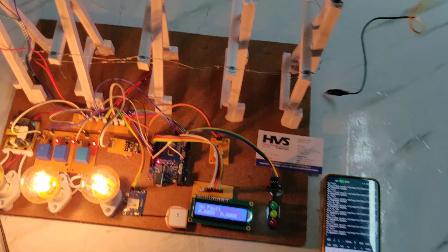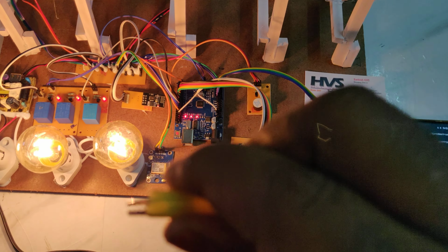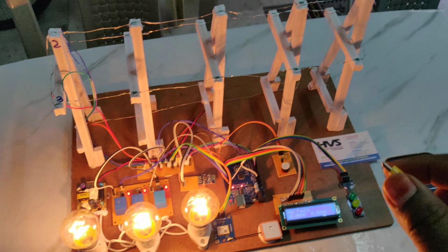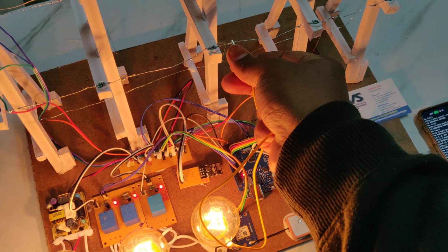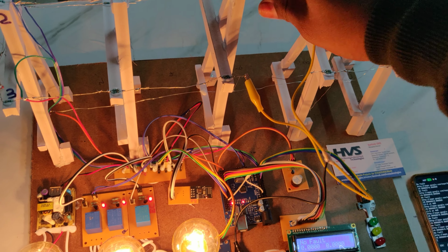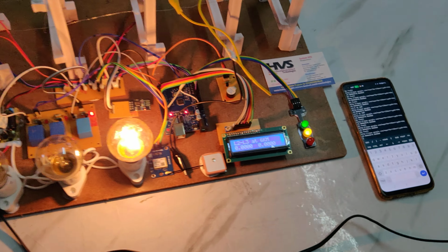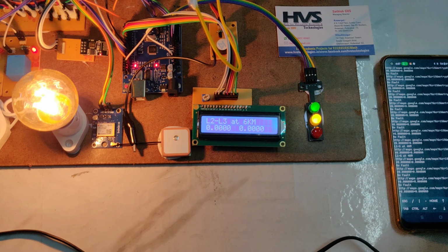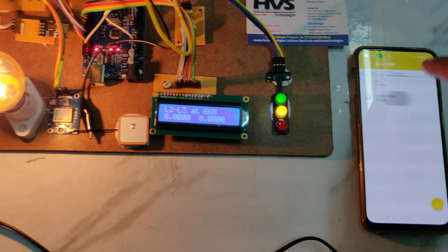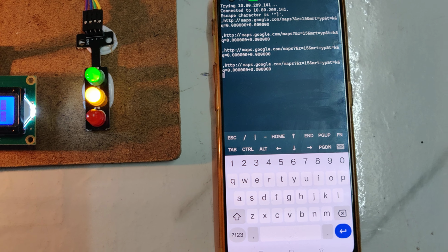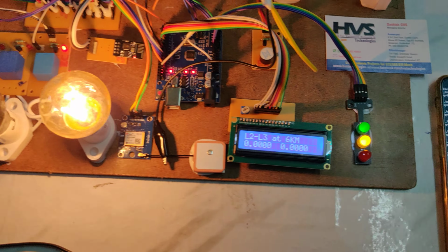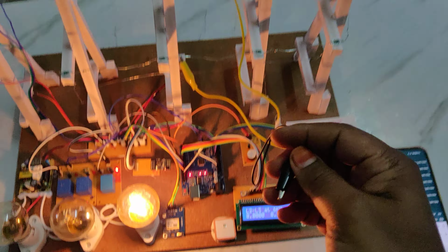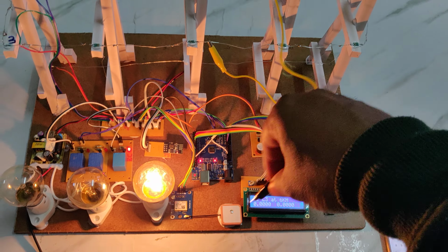When we demonstrate this, the crocodile pins are contact based, so we should touch them properly. If there is any loose contact, there is a chance of sparks and the values will fluctuate. During the demonstration, take care that these crocodile pins do not fall on any of the circuits.